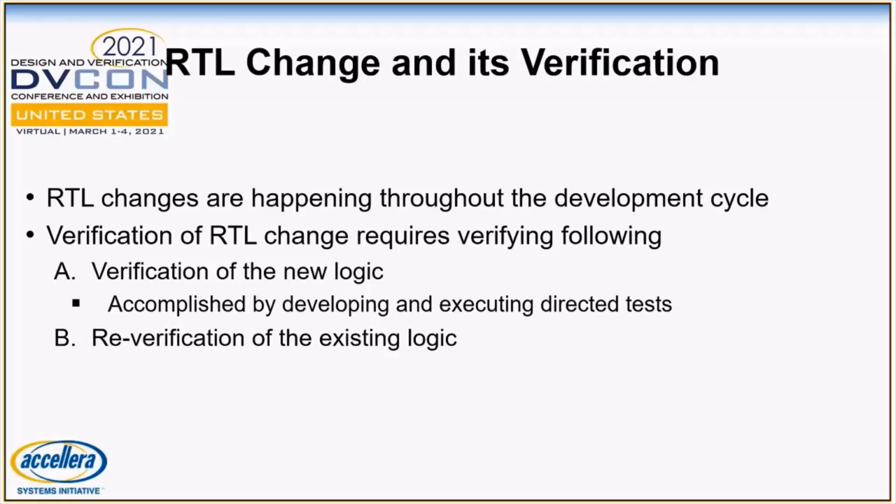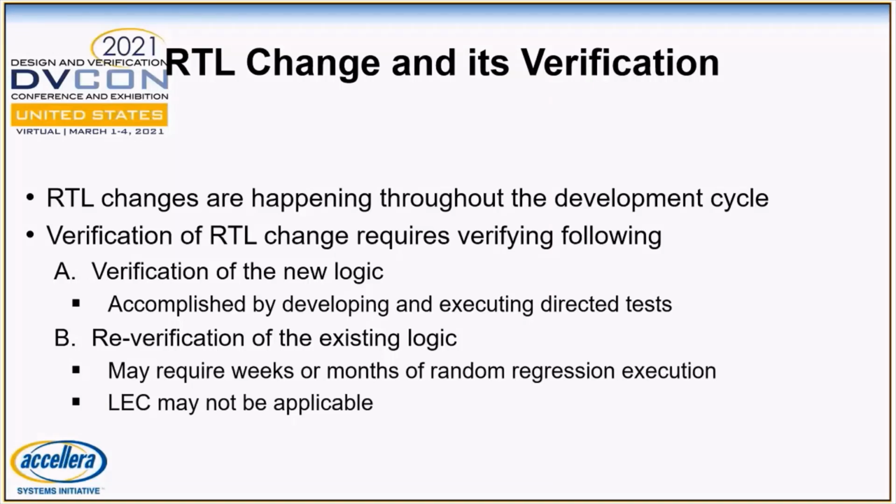However, re-verification of the existing logic is usually a major overhead and may require weeks or months of random regressions depending on the RTL change. One can think of using the LEC method to address this, but it may not be useful as LEC cannot compare non-state matching designs unless they are very trivial.